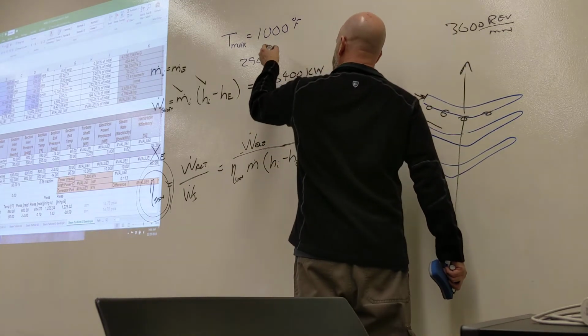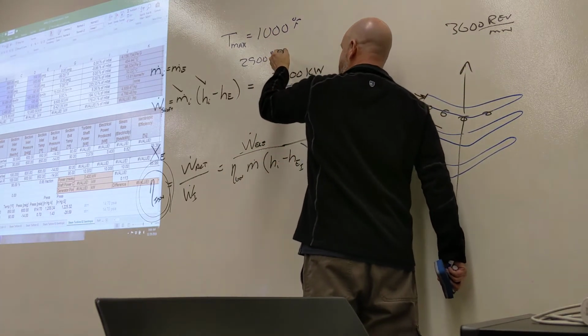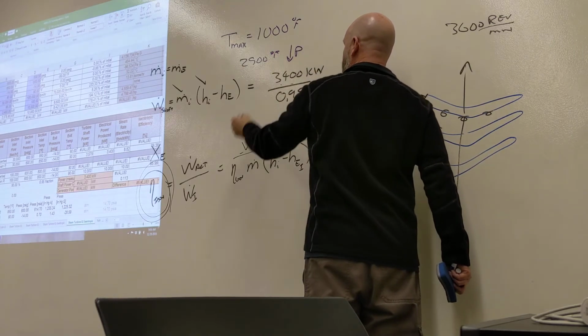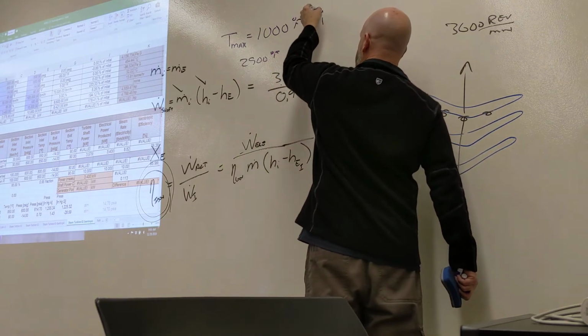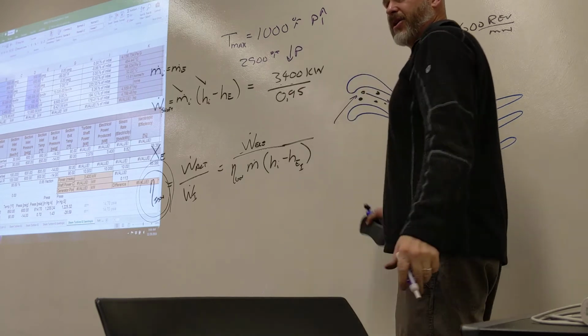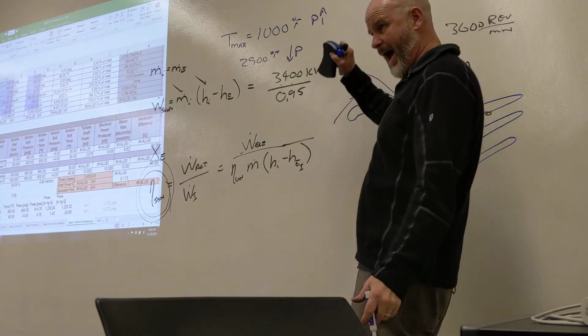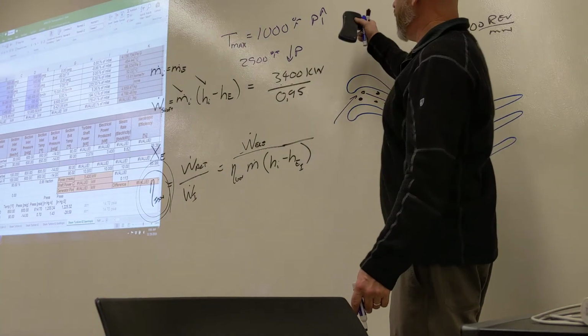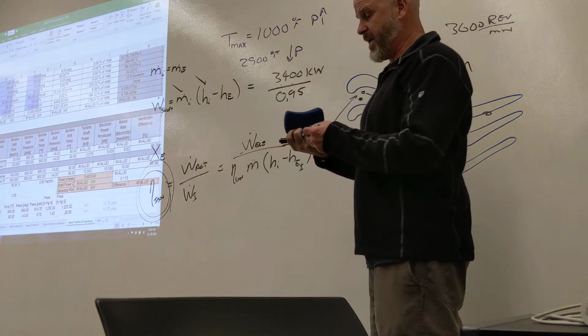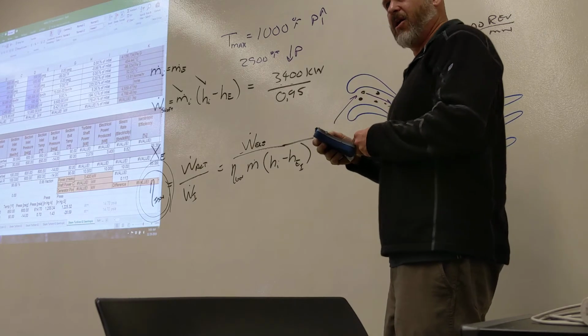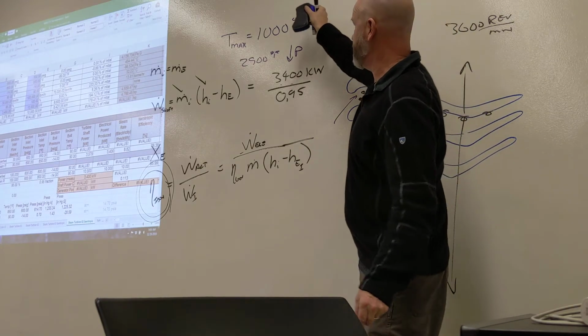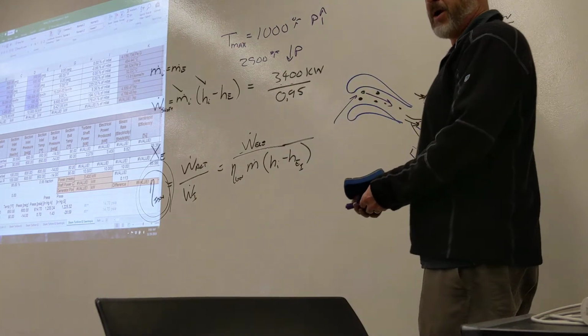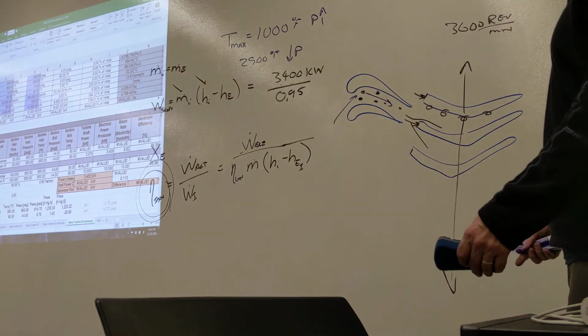The reason is, comparatively speaking, gas turbines are operating at lower pressure than steam turbines are. So we're doing higher and higher pressure on steam turbines, so we limit the temperature because the steels, the materials, cannot handle these super high pressures with much temperature over 1,000 degrees Fahrenheit.